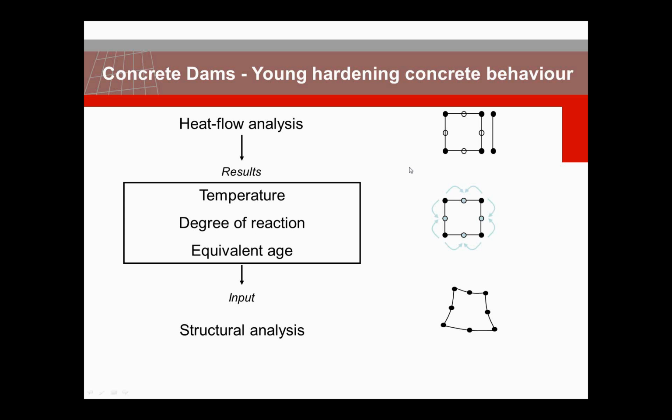Also nice to explain in this sheet is that DIANA always uses, in a heat flow analysis, elements which are one order lower in their interpolation function than in a stress analysis. We do that because that way we get the most accurate results, and we can avoid fluctuations in the stress fields. Because in a thermal analysis we calculate temperature fields.